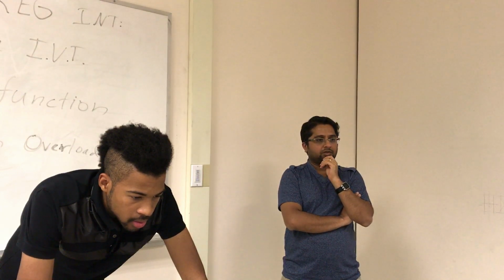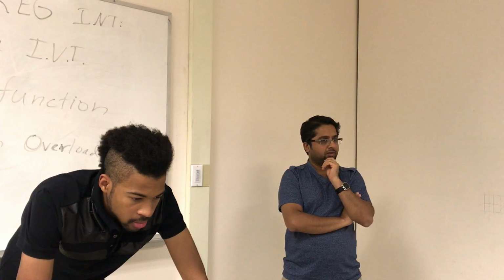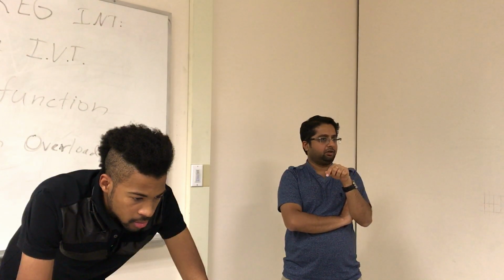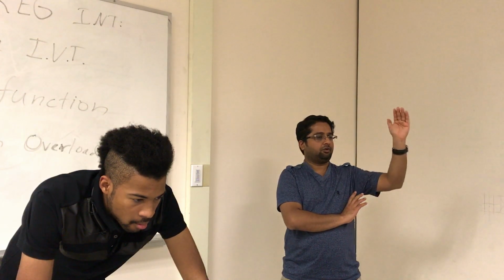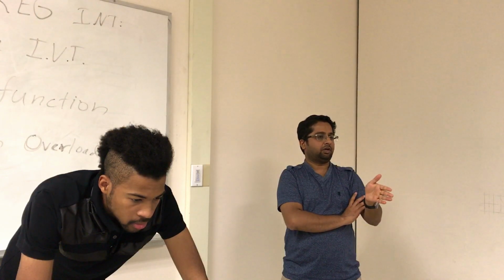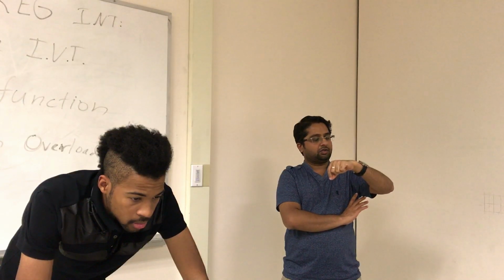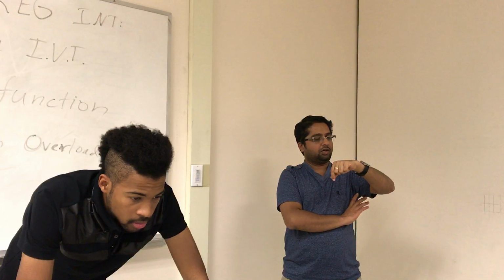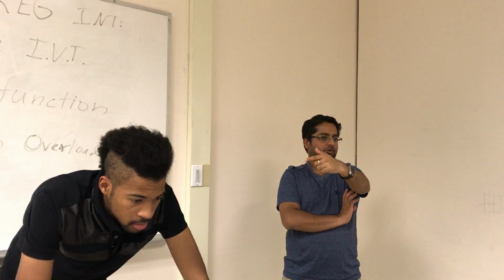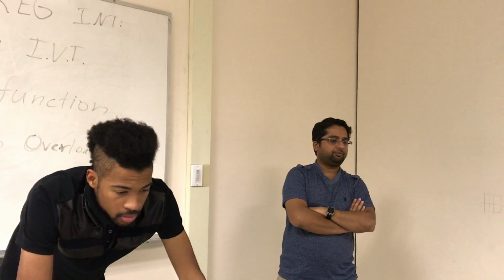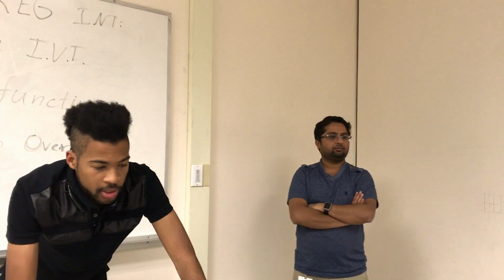Okay. So once that is done, then you will be sensing something on the signal, like a rising edge or a falling edge on that pin. You can use another GPIO pin to actually do that, where you set high for 500 milliseconds and then set low for 500 milliseconds. And then once the pin goes high, you can give that as a trigger to this pin, the input pin, which is going to call some other subroutine. Start off with one pin, get that to work, move on to the rest.